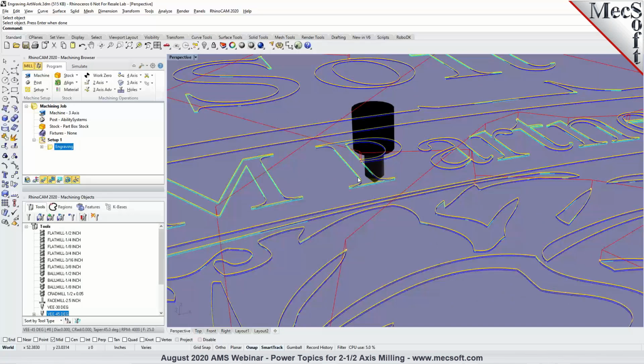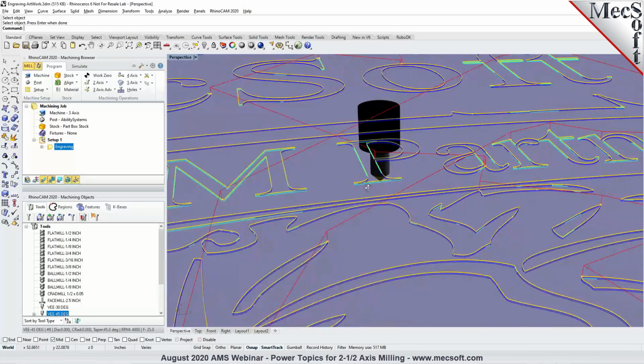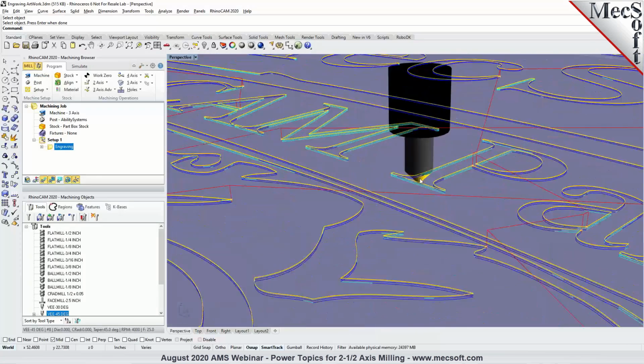that you selected. Yeah, so I just wanted to add one more to tie this back into the compensation discussion. So you can think of engraving as a toolpath method that does not compensate for the tool radius. All the other methods like profiling and pocketing, they actually take the tool radius into account and compensate by that amount. So the toolpath is actually off of the drive geometry by that radius. And that is by design.